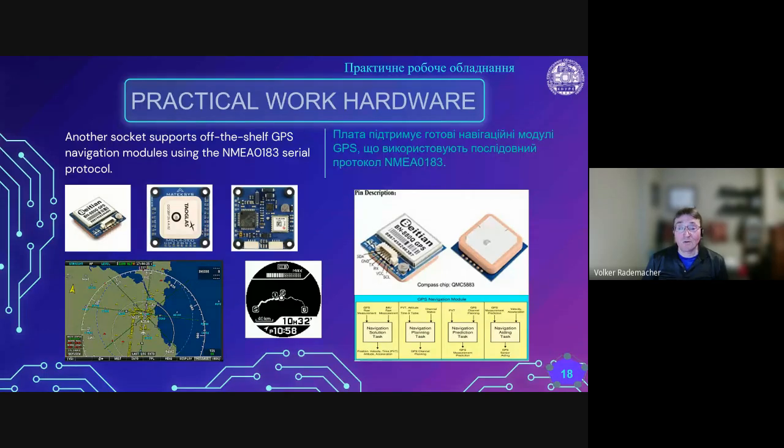That is what makes a module. What's the difference between just a module and just reading the string and having a system? Time, that is often underestimated. Quite often, a GPS module is being implemented solely for getting time. And you might be saying, okay, why would I use a GPS module for that? I can just use a real-time clock. They're cheap, no problem. The problem is setting the clock.